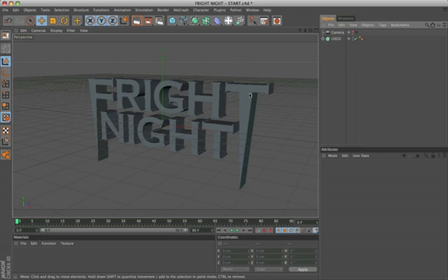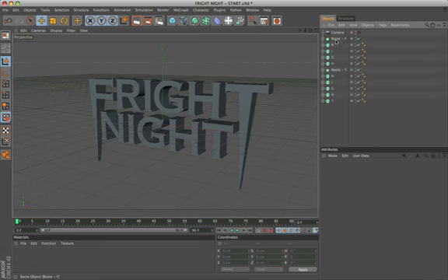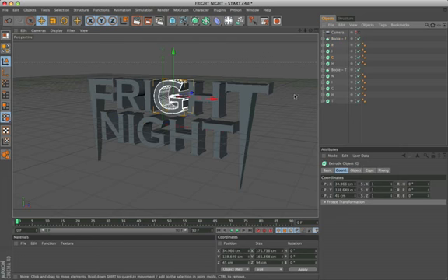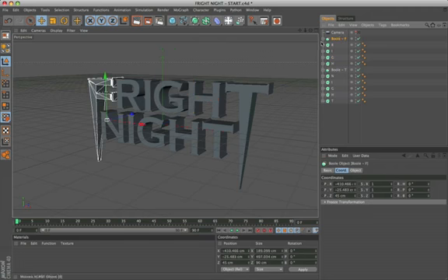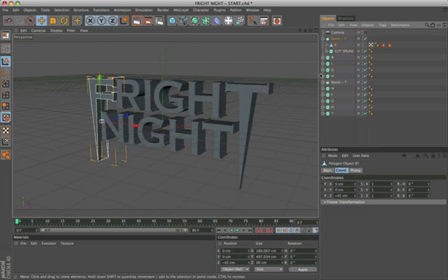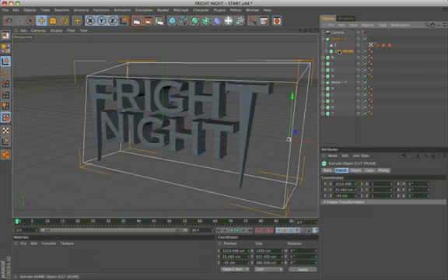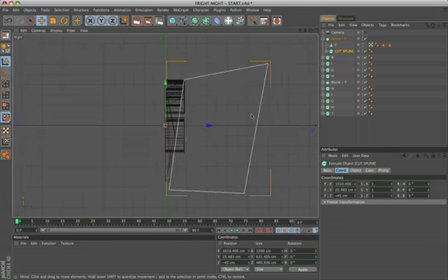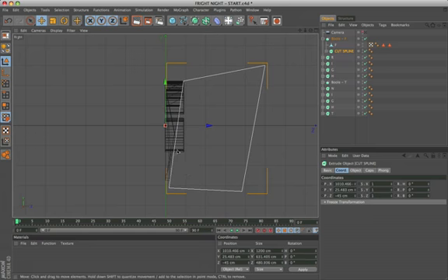We proceed with the next step, to change the profile of the letters F and T. First we need to divide all the letters, by pressing the C key of the keyboard. After, on the letters F and T, we apply the Boole tool, using as a cutting object an extruded quadrilateral, throughout the logo. You see, it has this corner, falling down. This allows us to adjust the cut that we want.